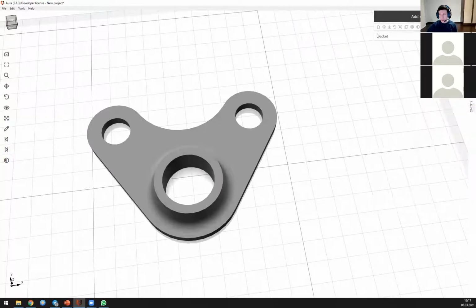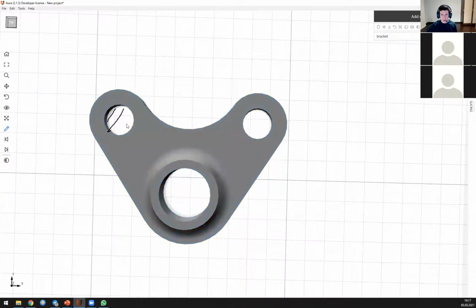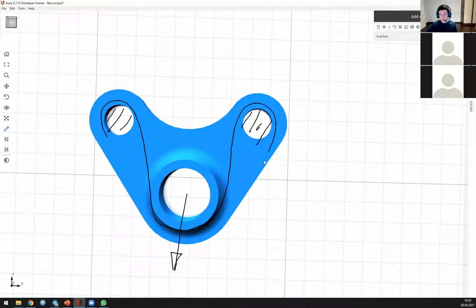And if you look at the material consumption, you have like 25 meters of fiber spent on this part. The better way is to use a mask here. So if I have this hole fixed and this hole fixed and the load coming here, I can put the fiber on this trajectory so that this fiber will connect the fixed holes with the loaded hole by straight lines. So the fiber will work under tension, and that will be the most effective reinforcement scheme for this part. So we can make a mask like this.